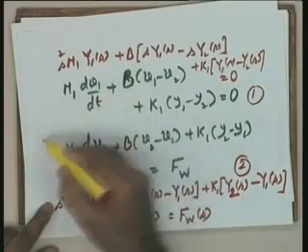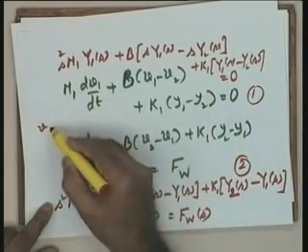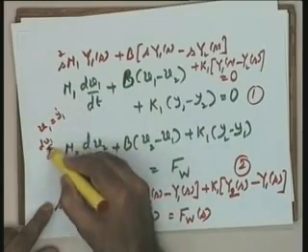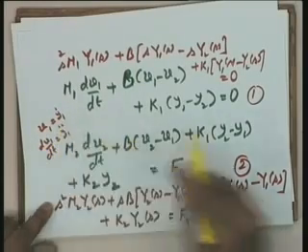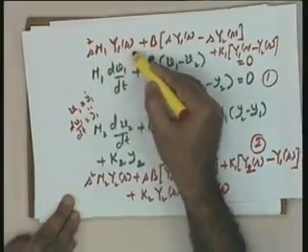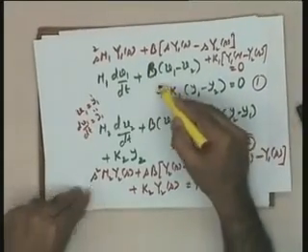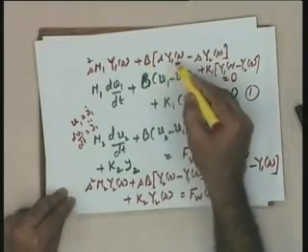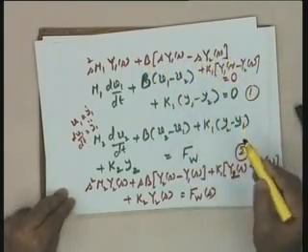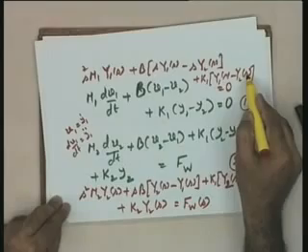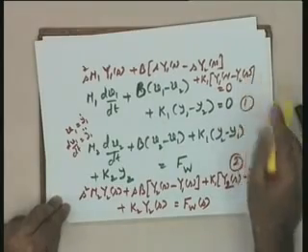v1 is the velocity. So, v1 is equal to y1 dot, or dv1 by dt equal to y1 double dot. So, this is m1 y1 double dot, hence I have written s squared m1 y1(s). I hope this is okay, plus what is v1? v1 is y1 dot and therefore b s (y1(s) minus y2(s)), and this is simple, plus k1 into these variables in Laplace domain. I hope this is okay now.